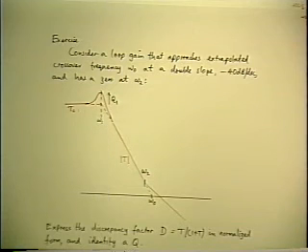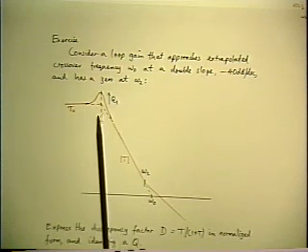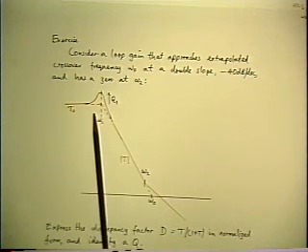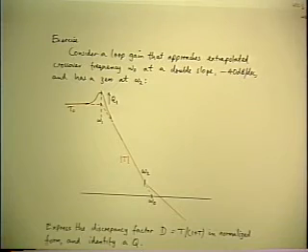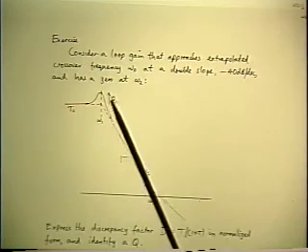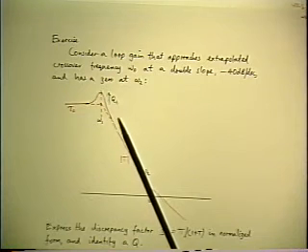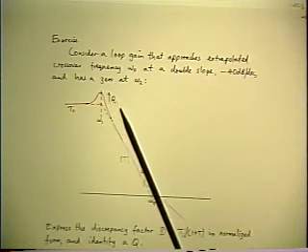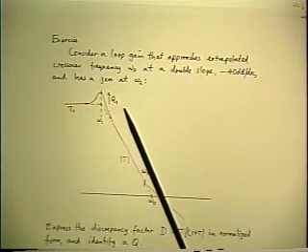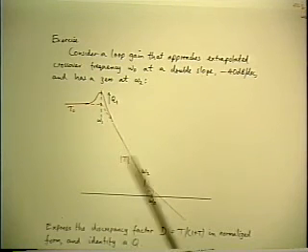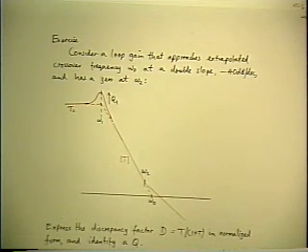If you don't do anything else with frequency compensation, then the loop gain would consist simply of this second order two-pole filter, which means that when you close the loop, you're going to cross over on a double slope, the skirt of the LC filter, and you wouldn't have any phase margin. So you'd be on the verge of instability before you've done anything else at all.